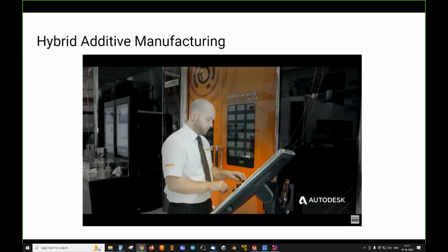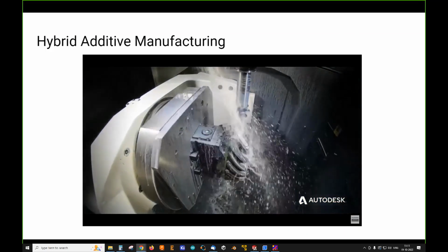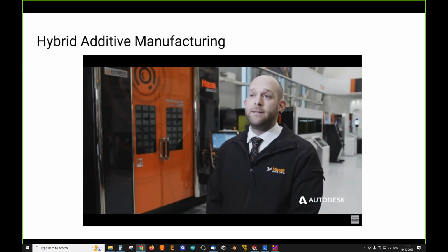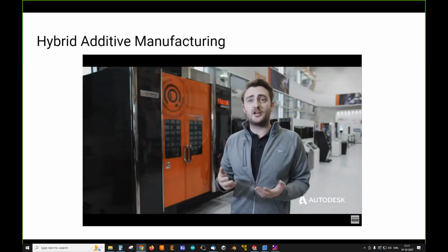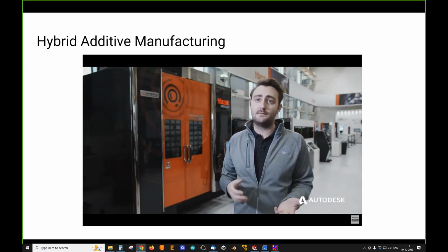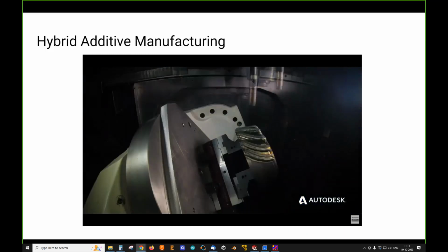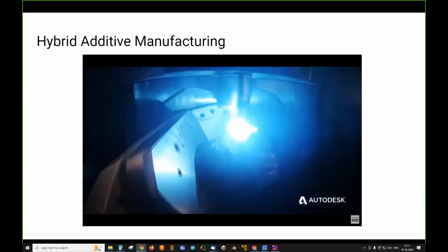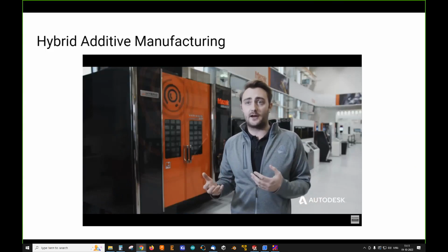This costs a lot of money in machine time as well as tooling. So the great thing about this technology is building the net shape, so you have a lot less material to be cutting. Hybrid manufacturing has several challenges. One of these challenges is around managing heat input into the process. Heat input in the process leads to a lot of internal stress in a geometry, and this can lead to distortion of that geometry, or in some cases, cracking or failure of that component.